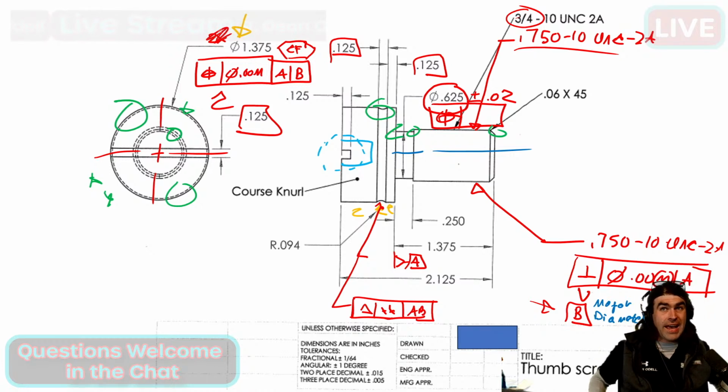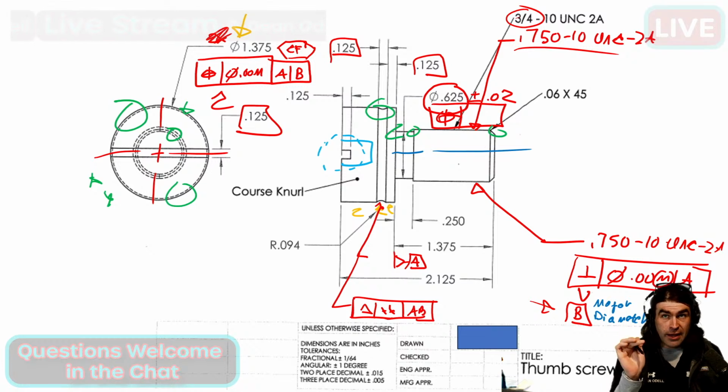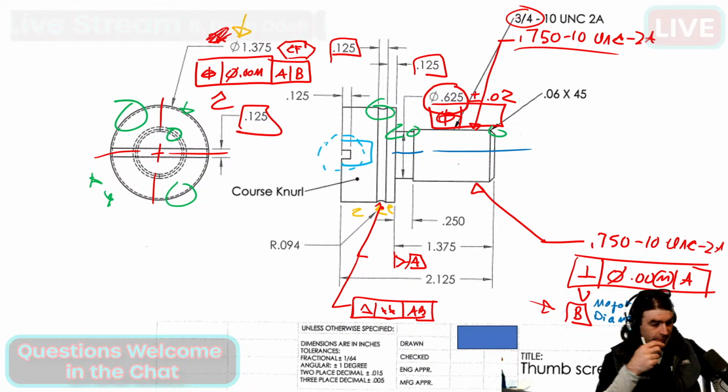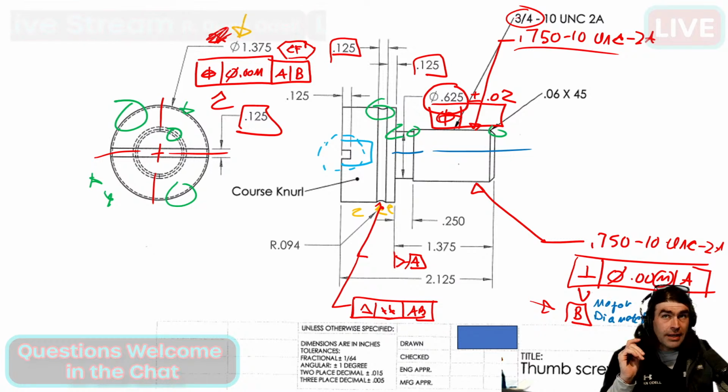I just think it looks bad, crowds up your drawing. So in SolidWorks, you would right click on that view and go down. There's something that says tangent edges off. There's like 3 options, but you want to turn that off. Where it sucks with SolidWorks, and I'm sure 100% of people are better than me at SolidWorks, right? I don't claim to be an expert or anything.